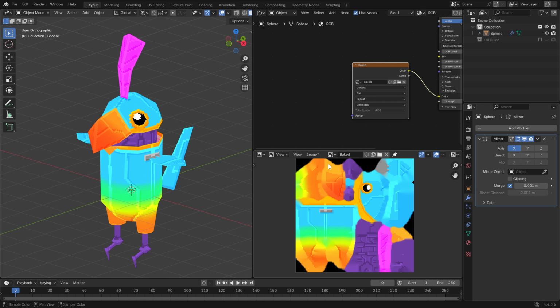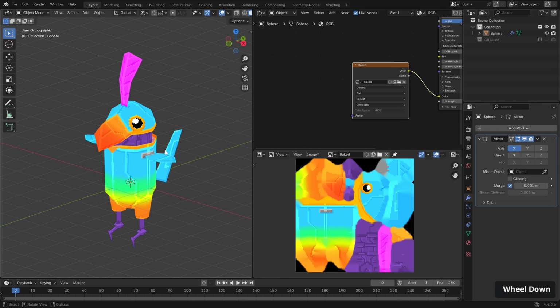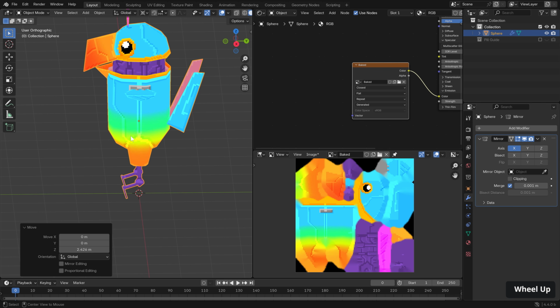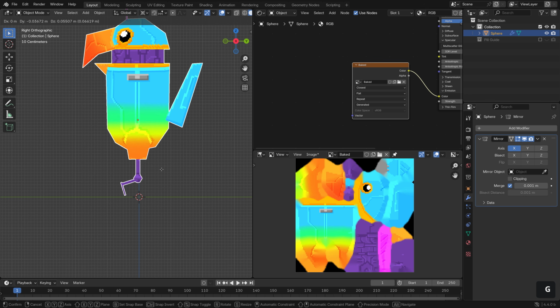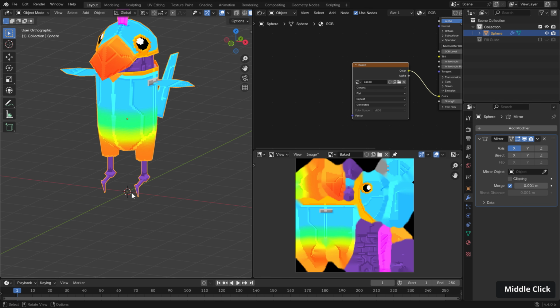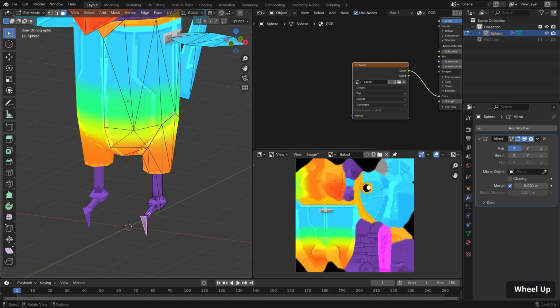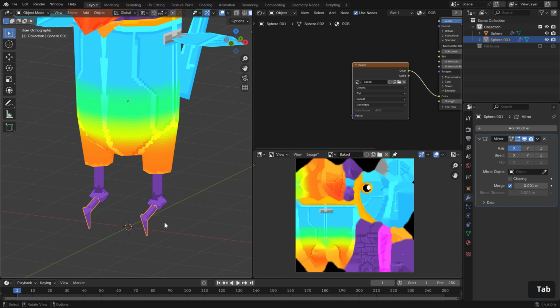Okay, it's time to move on to rigging, but firstly we need to make sure all of our geometry is okay. And to do so, first of all, let's hit G and move it up just to make sure it is above the ground ever so slightly. And we can jump in and separate our toe here with P on the keyboard.